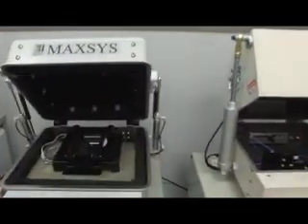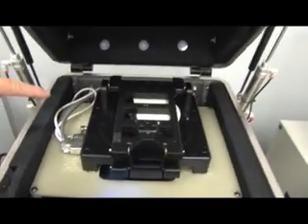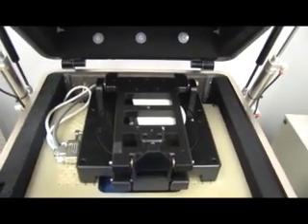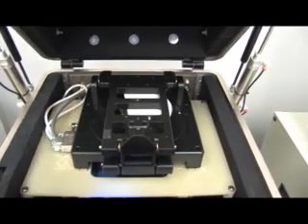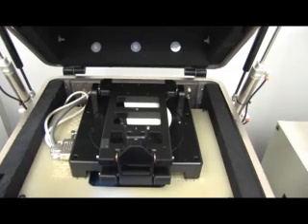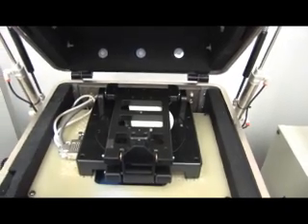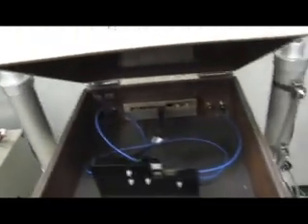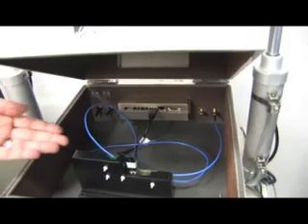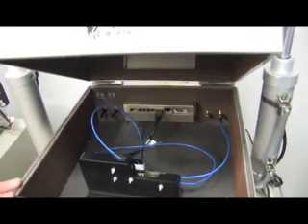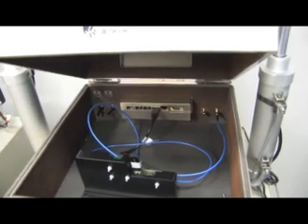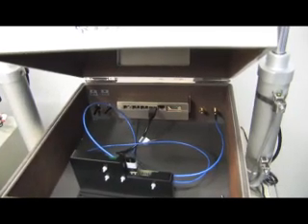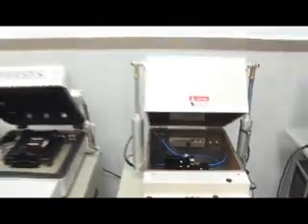You can look inside this one here, and inside this black fixture we have a wireless mouse radio board, and we have an RF chamber in the foam just like you saw in the previous test setups. And over on the one on the right we have something similar. We have an RF box, and you can see one of our devices under test, that dongle, and it will be transmitting to another antenna inside that black fixture. And when we run these on the factory floor, we'll be checking the transmitter's power, we'll be checking the transmitter's modulation and frequency stability. We'll also be checking the receiver's bit error rate and sensitivity.